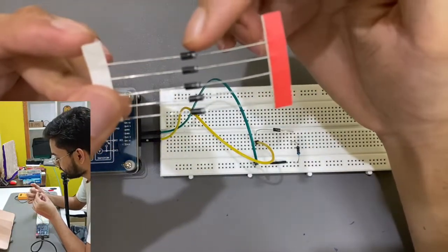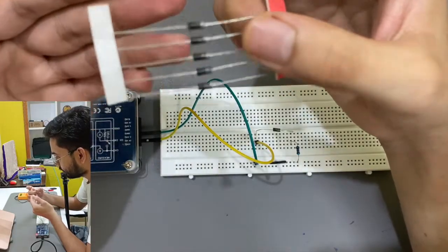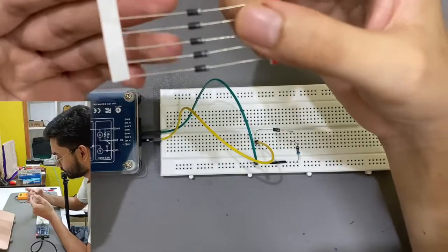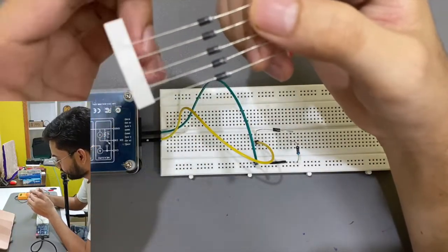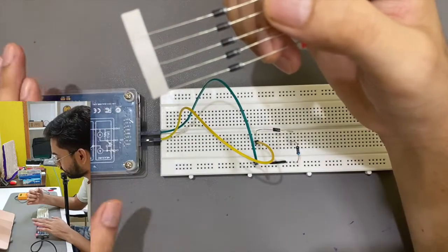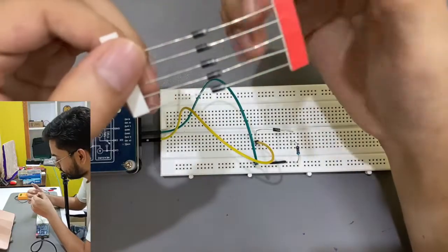But this diode is a real diode, and it's called a PN junction diode. So this kind of diode has some barrier voltage, which we also call voltage drop. Suppose the barrier voltage of this diode is 0.7 volt. So to flow current through this diode, the value of the external voltage should be greater than the barrier voltage, or voltage drop, meaning greater than 0.7 volt. Then this diode will allow current to flow through it.